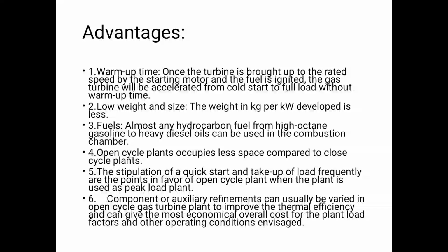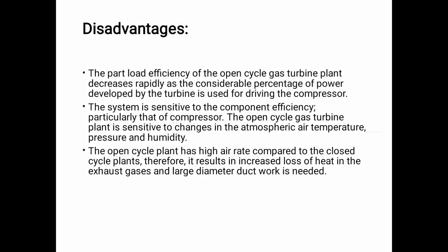The stipulation of quick start and taking up the load frequently are points in favor of the open cycle plant. When the plant is used as a peak load plant, component or auxiliary refinements can usually be varied in the open cycle gas turbine plant to improve the thermal efficiency and can give the most economical overall cost for the plant load factors and other operating conditions.